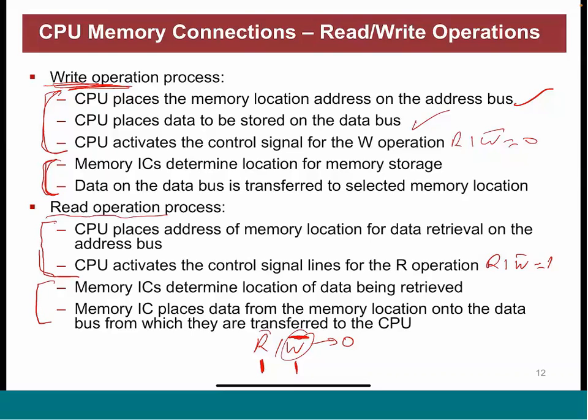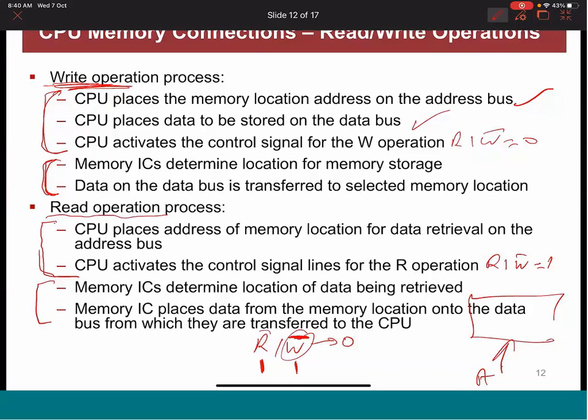Thank you. W bar means active low for write, and active high is the normal logic for read. Normal logic for read is the inverse for write. But again, it's just a notation. I can just call this pin A. It doesn't matter, right? It's just a name. So A is read when it's 1, and write when it's 0. For us as humans, it's good: when we put a bar, it means it's active low.